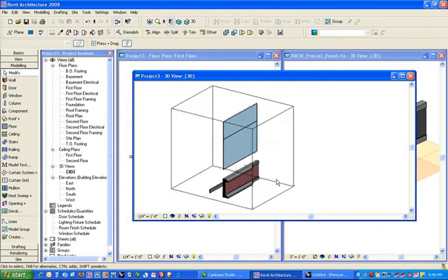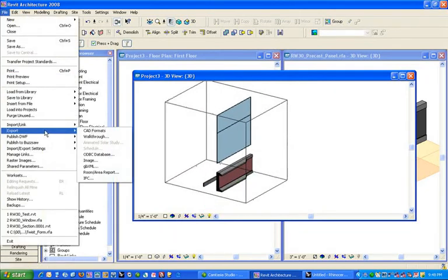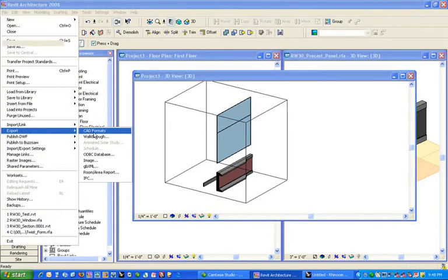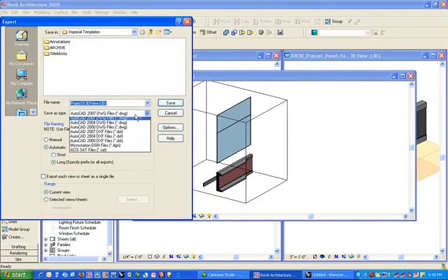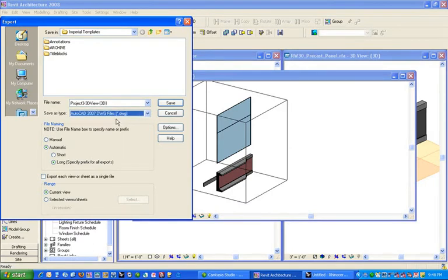So now let's export this out as a couple different options. So here under CAD formats, you have DWG and SAT, and DGN if you're using MicroStation. The DXF, I just use the DWG for the most part. So in DWG you have a couple options. File naming, this is more important when you're exporting sheets. You want them to name automatically like your drawing set. It organizes them because you can do multiple files at once.